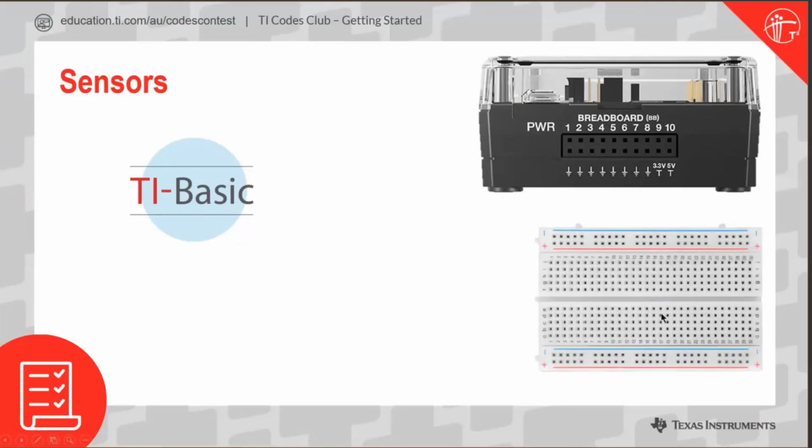So there's a little breadboard pack you can buy. So that's the little breadboard essentially that comes with it. I've got a little variable resistor attached. I use that same one in the engineering project. And the first thing we do is connect a negative or earth to one side, and then I'll connect the positive to the other side. So this gives me a reference voltage.